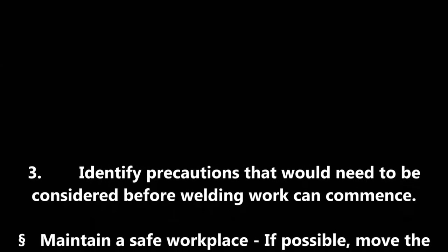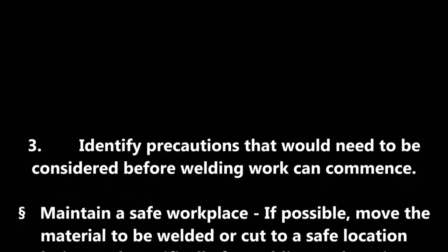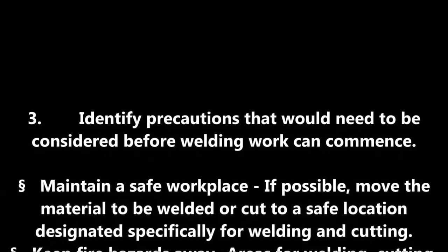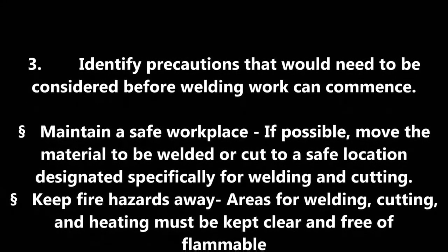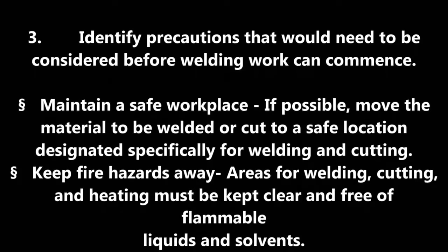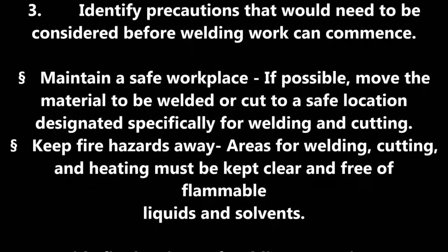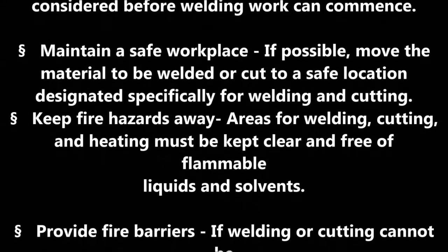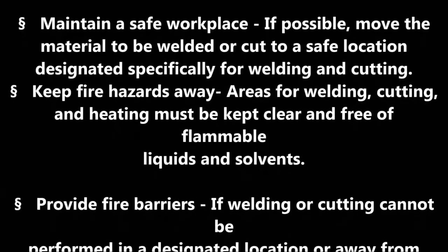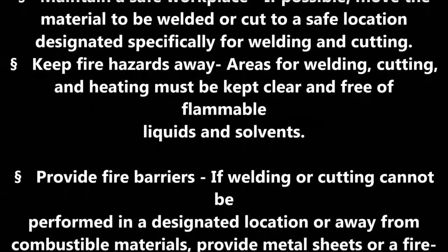3. Identify precautions that would need to be considered before welding work can commence. Maintain a safe workplace, if possible. Move the material to be welded or cut to a safe location designated specifically for welding and cutting. Keep fire hazards away. Areas for welding, cutting, and heating must be kept clear and free of flammable liquids and